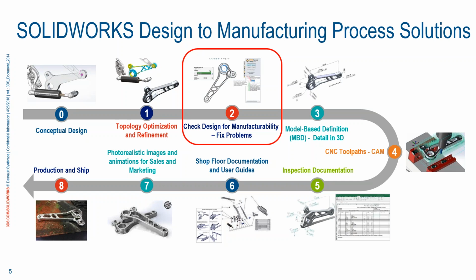Now, most companies are doing 2D drawings. That has been our legal document for 100 years. But there is a new technology emerging, and that is model-based definition. It is a standard where we put our manufacturing tolerances directly on the 3D model and send that 3D model with the tolerances directly to the CAM operators. So the CAM toolpath is directly on the SolidWorks model, reading our tolerances. So there's no need for 2D drawings. We do model-based definition documentation with a 3D PDF and include the 3D model there with all the information needed. This is a very good process, very fast and very accurate.